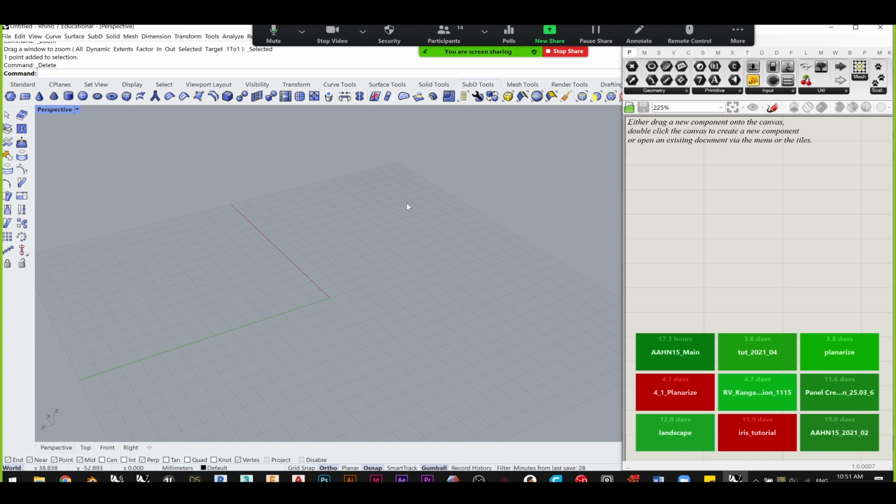It is going to be what I would like to call close enough, right? And that is good enough for us. So I'll begin by just creating a box, SubD box, and I'll make sure that X count, Y count, and Z count, all three of these are set to be 1, meaning that there's no subdivisions for the box. And I'll start from 0, so I'll just type in 0. And here I'll just type in the dimension.